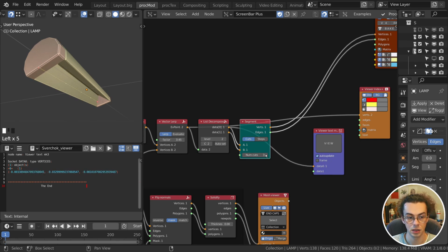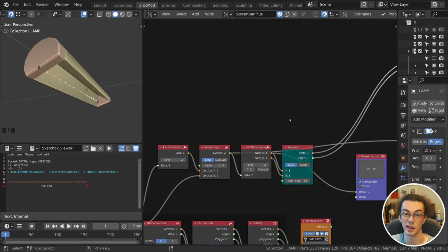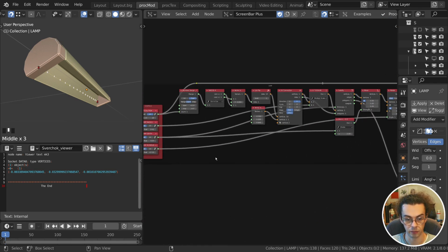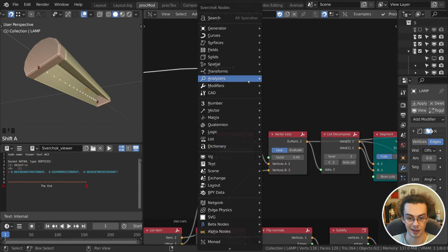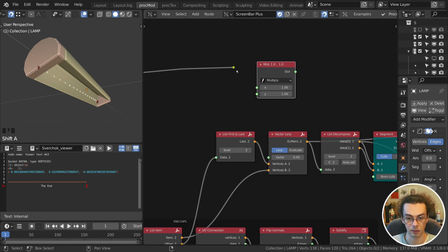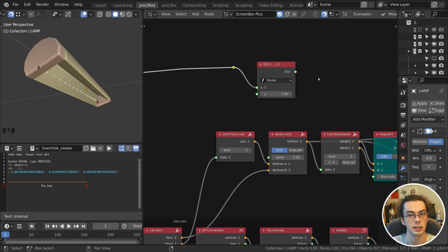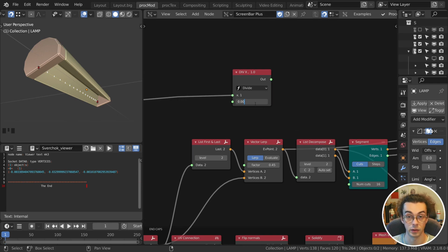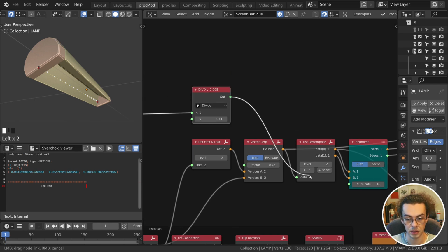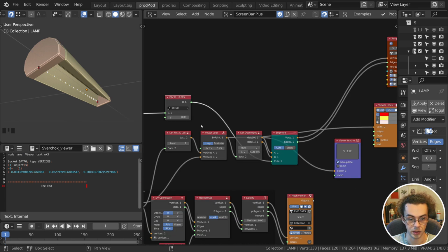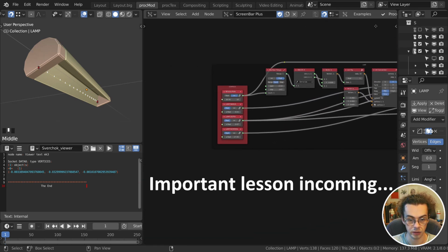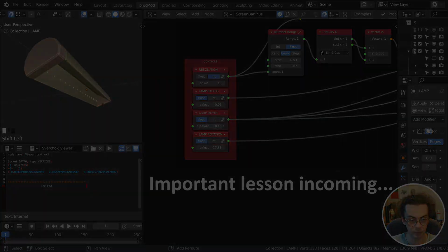The number of cuts is going to generate vertices, and these are going to be the positions of the LEDs. If I have the length of my lamp, which I do here, now if I take a number scalar math and I plug this in, change this to divide, and we're going to divide it by the distance in between each vertex, which is around about 5 millimeters, 2 zeros and a 5. And then if I plug this into my segment, you now see that when we change the depth, okay,